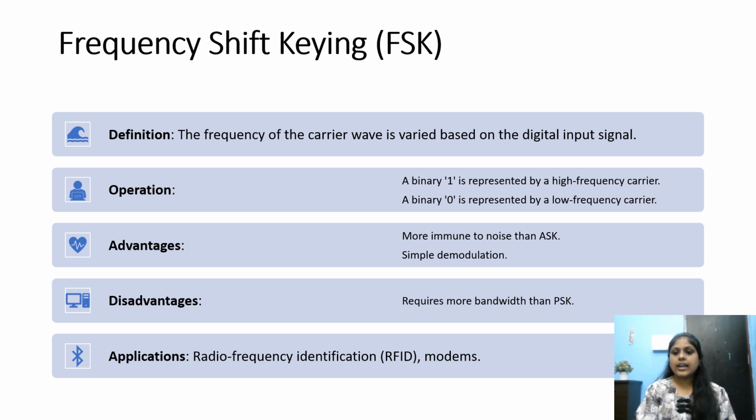Frequency shift keying, FSK. The frequency of the carrier wave is varied based on the digital input signal, and the operation includes: a binary 1 is represented by a high frequency carrier and binary 0 is represented by a low frequency carrier.